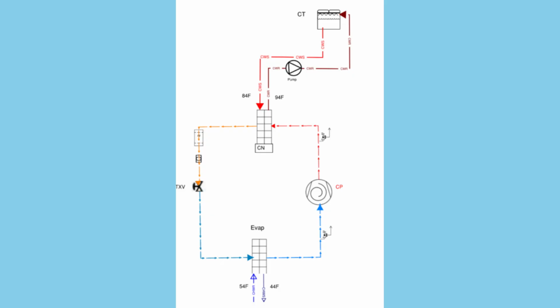As load decreases, both range and approach narrow, meaning colder water can be supplied back to the condenser. However, at low wet bulb temperatures, tower control becomes critical to prevent overcooling and freezing. Tower fans are often equipped with variable speed drives for smooth control. Proper chemical treatment prevents scale, corrosion, and biological growth, protecting long-term performance.